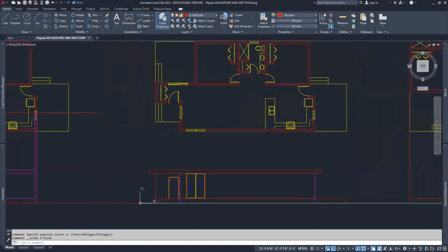Let's say that instead of a flat roof, I wanted to put a hip roof. A hip roof actually has the slope on all four sides. So whatever slope I see in this elevation, I'm also going to see the same one on the other side. In architecture, when we draw roofs and slopes, the slopes are always based on a rise versus a run. If I go across 12 inches, I could come up 3 inches, and that's going to give me the slope that I would want.